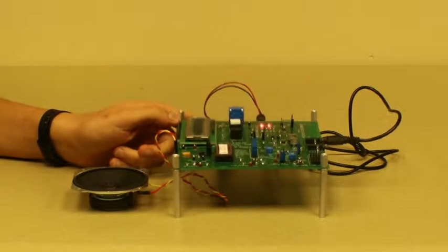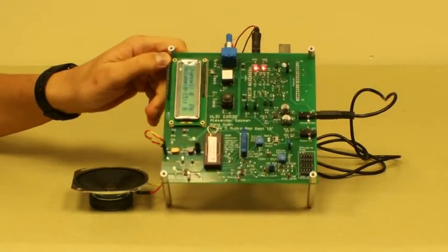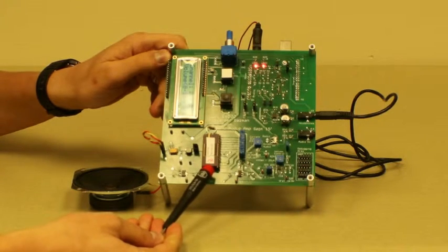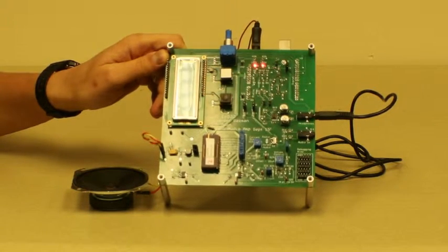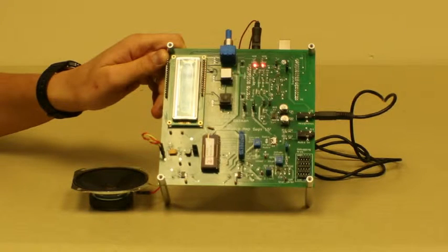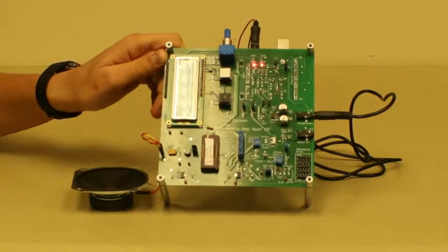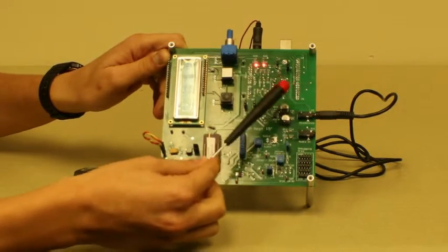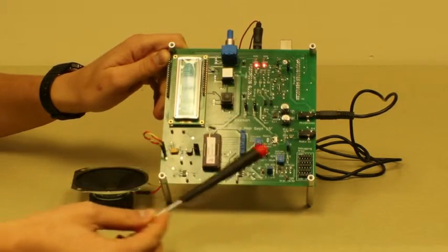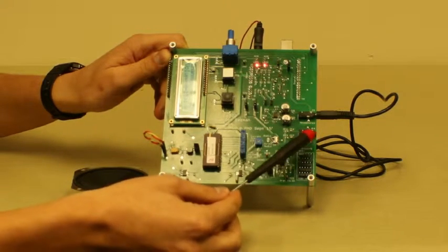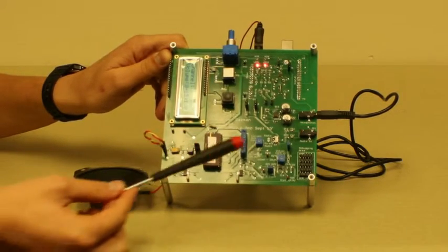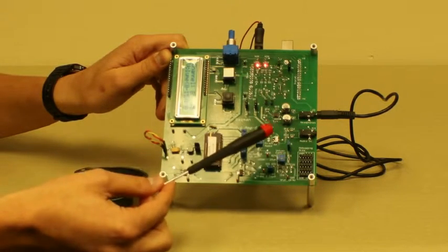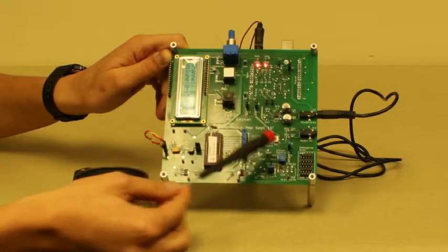Now I'm going to present the PCB that we designed to test our Class D audio amplifier. The audio amplifier chip is over here in the bottom. We designed this board to have two audio signal inputs to the amplifier. We can either have an FM radio audio signal coming in, and the radio circuit is on the top right, or we can have a direct audio input from a 3.5 millimeter jack from here. The two audios can be switched, and the user can choose either to listen to the radio or from a direct input through the switch over here.